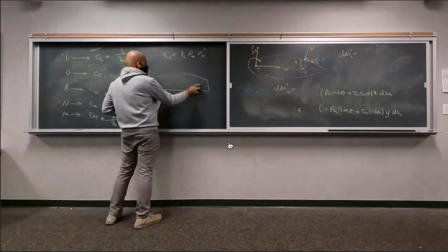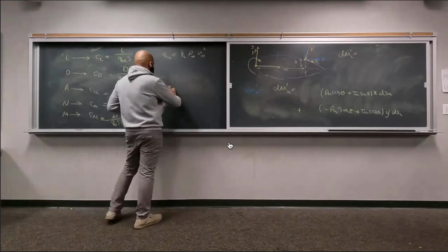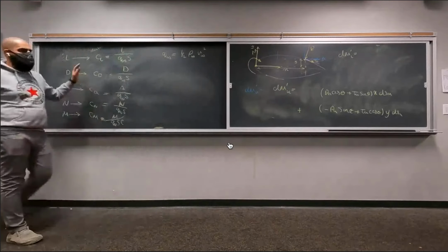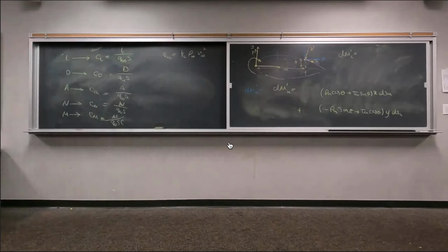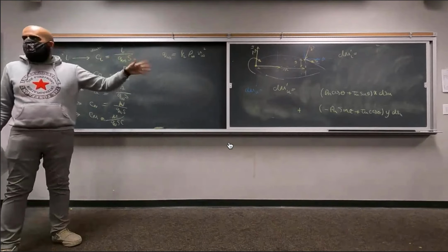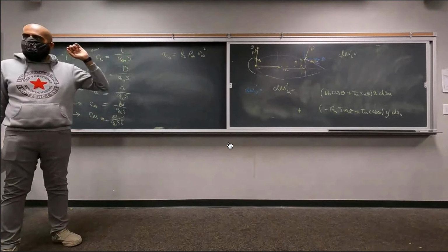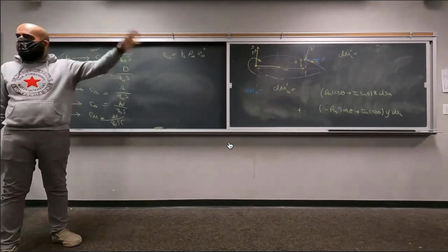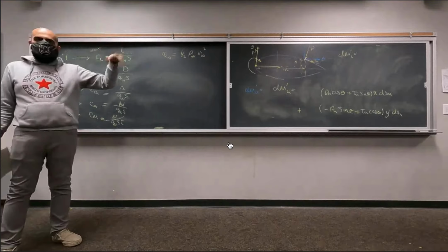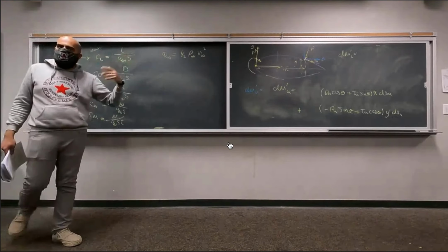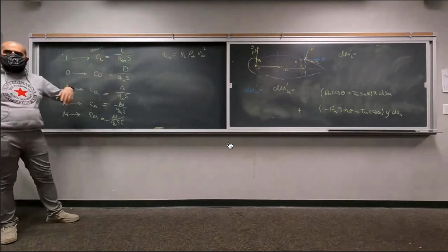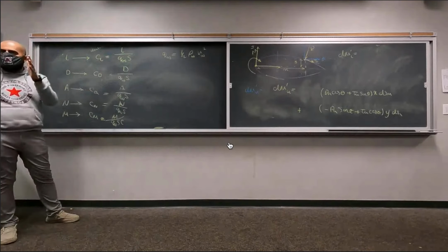One thing that we have to mention is the other definitions we have for these coefficients. If you recall, we were dealing with the per unit span parameters, like lift per unit span, drag per unit span, or per unit length, if you will, normal force per unit span, all of those things. But here we have lift and drag on the complete force, not just the per unit span force.